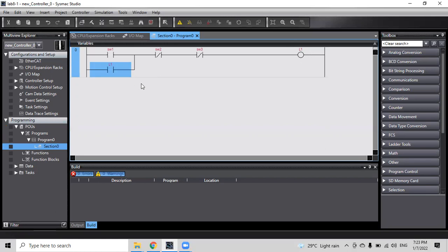This is actually a very special thing about the PLC ladder diagram. Only in a ladder diagram do you have this kind of thing. We call this a latch. Let's just imagine we don't have L1 here. We turn on this one, close this one, and then we see the output is moving.